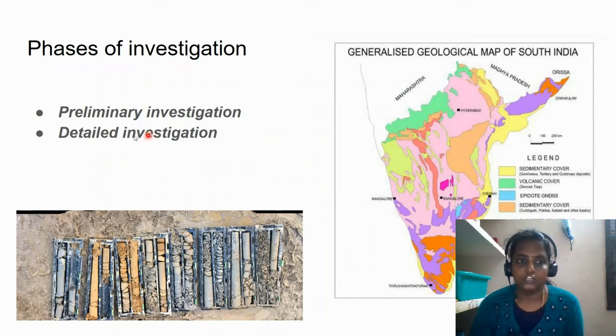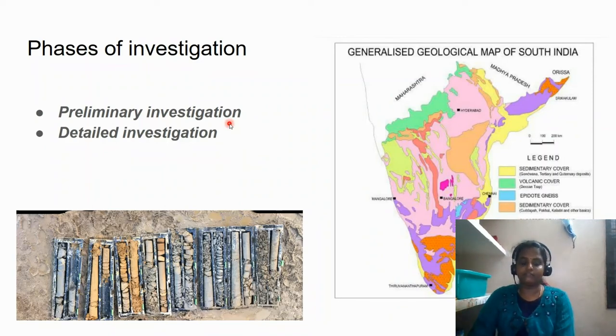Just like a doctor treats us, we treat the soil. So in a preliminary investigation, we'll be collecting maximum information. Then, when we finalize the site, okay, these are the two sites where I'm going to build, then we conduct the detailed investigation. That is where we go and collect the soil sample or rock sample.